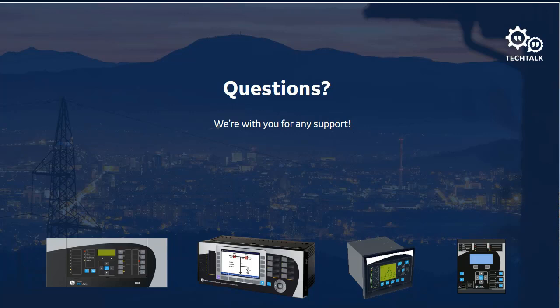where I'm closing up the delta, I run those 2 wires out to a device, and those 2 wires on that broken delta will have zero sequence voltage on it. If you have an ungrounded system and one of your phases becomes grounded, you will be able to see some voltage on that broken delta set of VTs. And so you can use that system to detect a grounded phase on an ungrounded system.